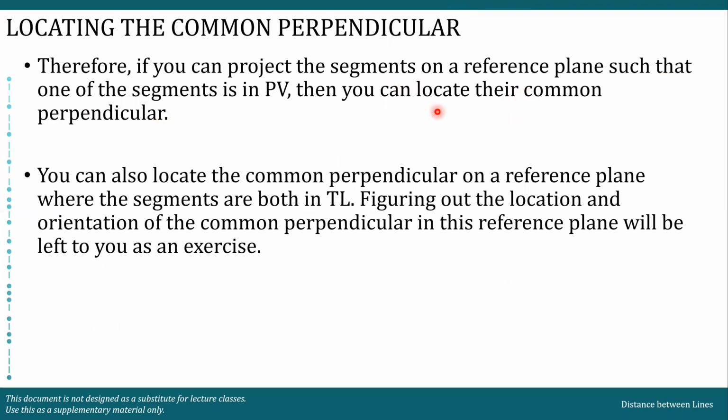Therefore, if you can project the segments on a reference plane such that one of the segments is in PV, then you can locate their common perpendicular. Hindi to pinakita, pero i-state ko na rin, you can also locate the common perpendicular on a reference plane where the segments are both in TL. Figuring out the location and orientation of the common perpendicular in this reference plane will be left to you as an exercise. Naalala nyo, I think it's plate number 6, if I'm not mistaken, you were asked to draw a reference plane kung saan parehong TL yung dalawang lines. Diba? So one application of that is looking for common perpendicular. Mamaya, dadaanan natin to. Dito muna tayo sa first bullet.